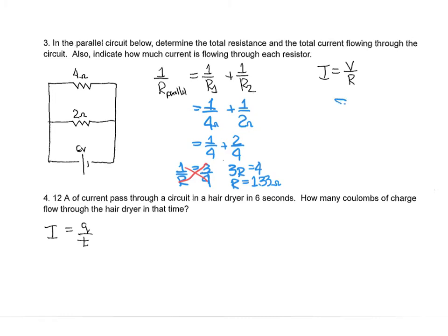All right, so current then, I've got a 6-volt battery, 1.33 ohms of resistance. So if I divide that out, 6 divided by 1.33 is 4.51 amps of current. And so again, when these amps start flowing around, that's 4.51 amps. When they get here, hey, some of those amps can go this way, some can go up here, right? So different amounts of current will go through different parts of the circuit, and then all that current meets up here and goes round and round.